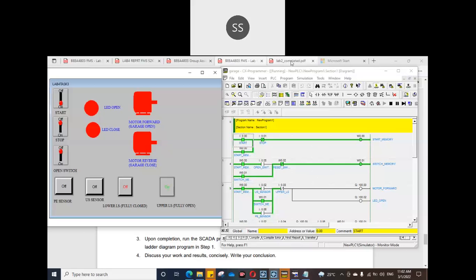Let's say you're taking your car out from the garage, so the PE sensor is hit because you are reversing the car, and the ultrasonic sensor is hit also. Once your car is out of the garage, the PE sensor is off. Then you have moved out of the range of the ultrasonic sensor, so the ultrasonic sensor is off. So you can see the motor is automatically closing. Instead of using a reset switch, we have made it automatic.